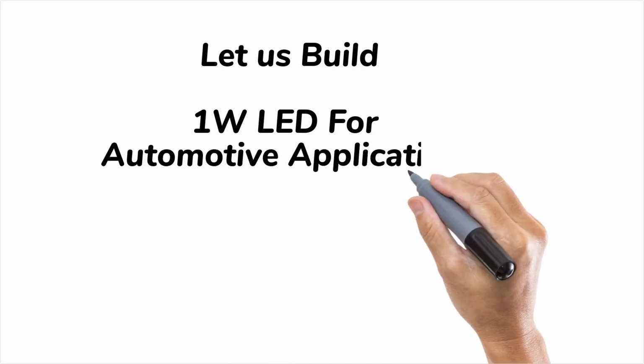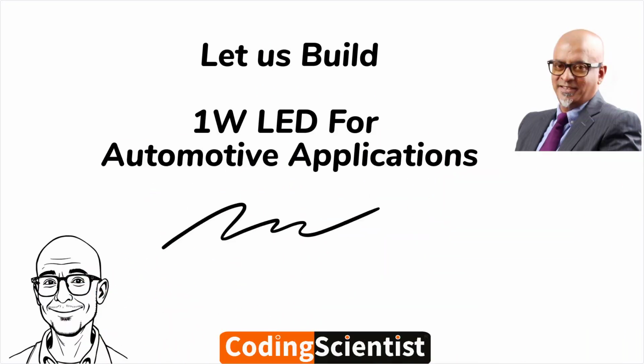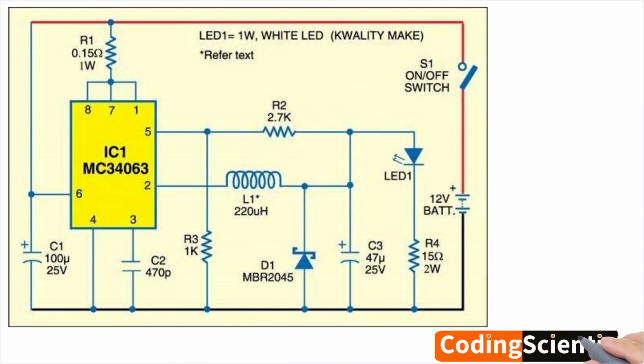Let us build a 1-watt LED driver for automotive applications. This simple circuit lets you run a 1-watt LED from the battery of your car. The MC34063 is used here as a buck converter. It is a monolithic switching regulator subsystem, intended for use as a DC-DC converter.